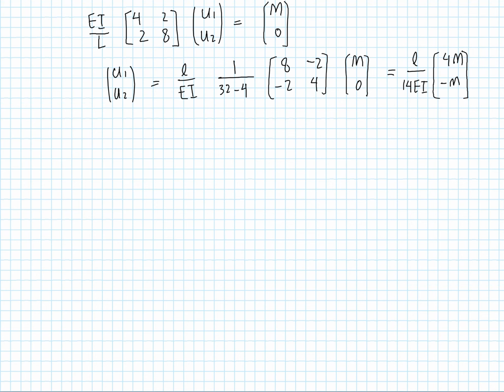So what I want to do now is to draw my beam again, and this time I want my beam to be deformed. So here it is. This is the double span beam, and the first thing I'm going to do is to draw the boundary conditions. Here it is. And what I want to do now is to draw the deformations. So if I'm looking at my calculated deformations, I got a positive deformation, and we said positive is counterclockwise.